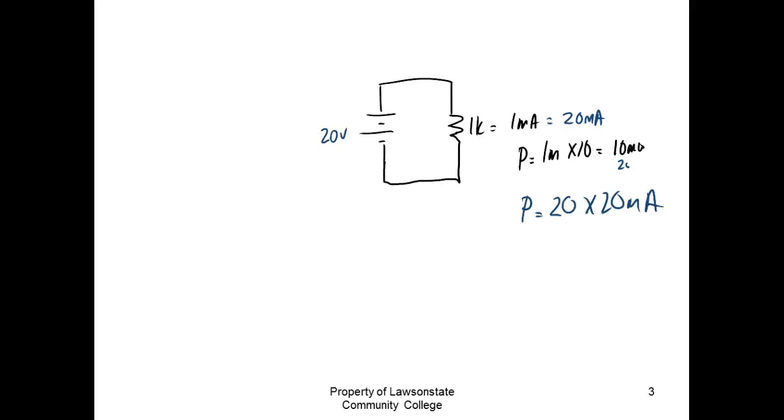I went out there and the thing had 120 volts on it instead of 240. So an 1800 watt element was only doing 1/4 of the power. It wasn't even getting hot enough to boil water. What happened is she lost one of the legs coming down from her transformer, so the element was seeing 120 volts instead of 240.